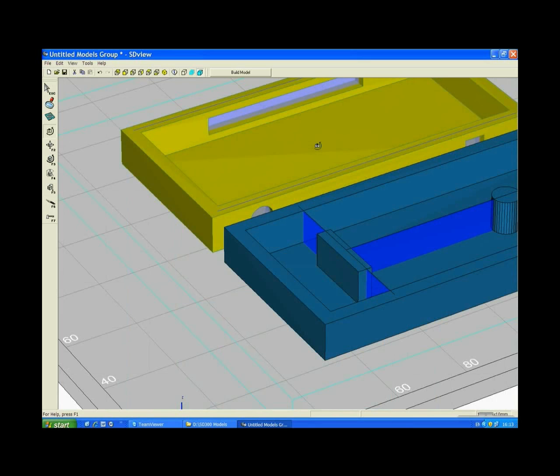When removing the support material in this part, you may remove support material from the inside of the part and then remove it from the outside of the part due to the peeling cut that now creates a cut in every opening. Of course, a peeling cut going through any model geometry will not cut or damage the model geometry itself, but will only cut a plane in the areas that are surrounding the part geometry.